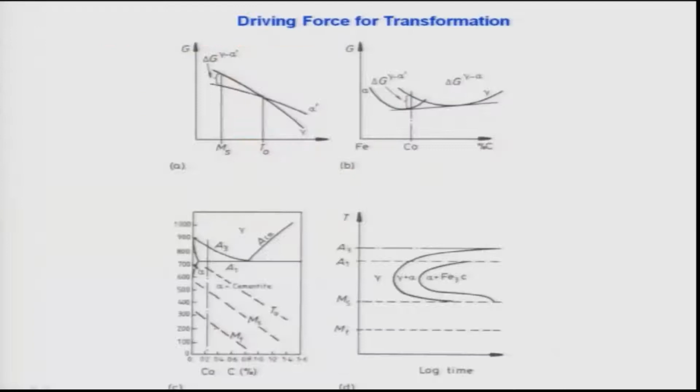But the question is this: how does this transformation happen when steel is quenched from the high temperature to water? Obviously, as I discussed, this is a diffusionless transformation. So, atomic movements basically occur because of the application of shear forces, but this is not so simple as you observe. As you see, there are plates in the martensites, and let us first look at how the driving force plays a role for the transformation, then we will get back into the crystallography of martensite transformations.